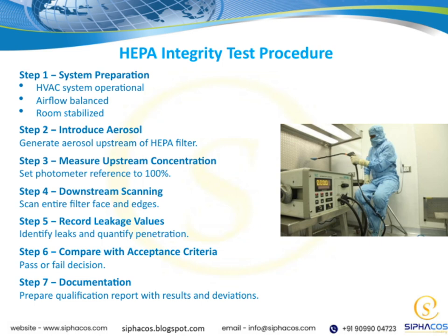Then, in Step 4, we perform downstream scanning. We carefully scan the entire face of the filter and its edges to identify any potential leaks or areas of concern. Step 5 involves recording leakage values. We look for leaks and quantify how much aerosol penetrates through the filter, which helps us assess its integrity.